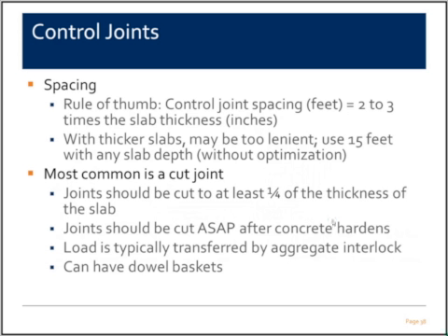Control joints. In the WJE world, we see the most problems with spacing of control joints. And in future webinars, we'll talk about some of the problems associated with excess joint spacing, such as increased curling, joint instability, random cracking, and so forth. But that'll be saved for future webinars. But spacing of these control joints is very important.